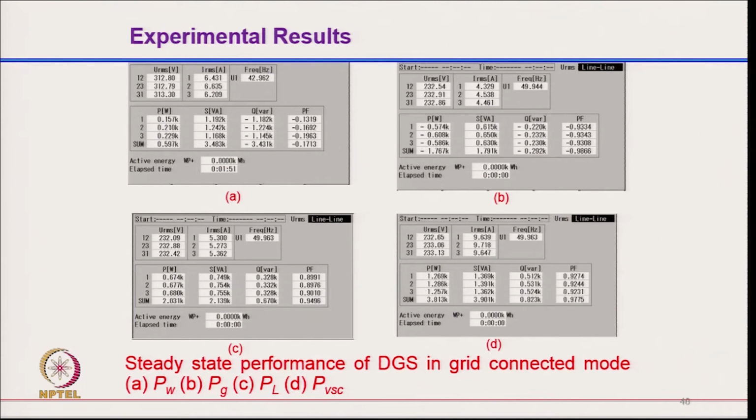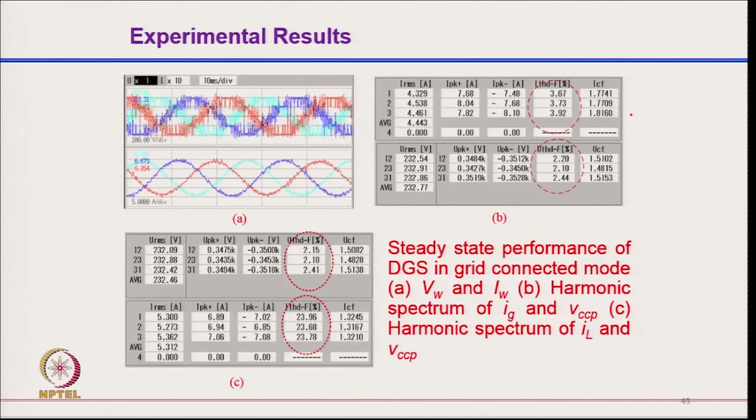So, here you have the grid current, typically the grid power, and you can have the quantities of the grid voltage, grid current, all the quantities here with the P and Q of the grid and power factor of the grid, closer to sinusoidal. Even if you have a kind of distorted voltage, you still have balanced sinusoidal current, and you have a quite good THD of the voltage and current. When the load current THD is quite high, you still have a grid current THD typically less than 5% here.